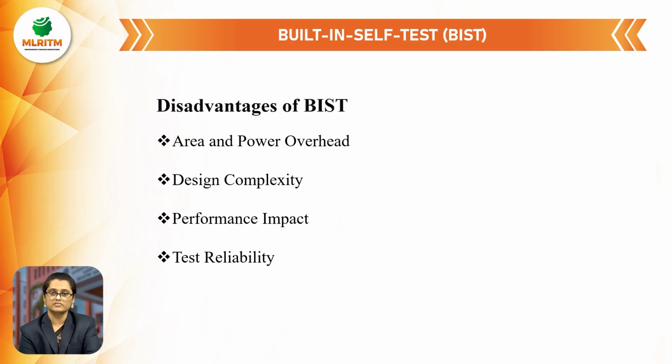And then the disadvantages of BIST: it occupies more area and power overhead, meaning we add additional hardware to the IC, and that's why it occupies more area and power. Design complexity, poor performance, and decreased test reliability are also drawbacks. So these are the disadvantages of BIST.